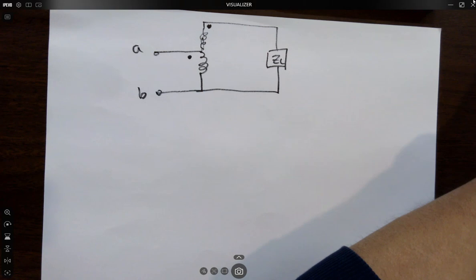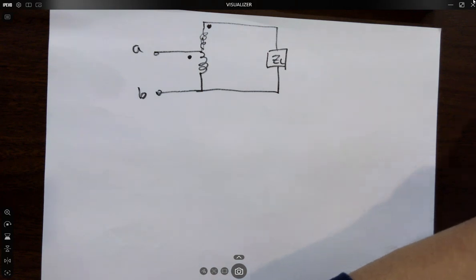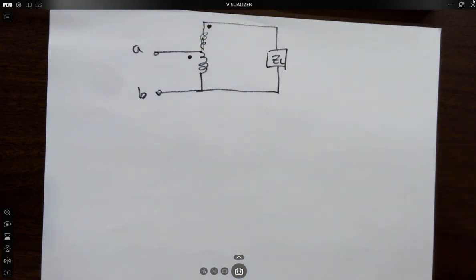Just a blinking LED of the audio signal of the song, received by the little solar panel. And the solar panel converts that blinking light signal into an analog voltage, and I use an audio amplifier to amplify it, and I can play the music using the solar panel that receives a blinking LED. It's a really interesting experiment to play with. So there's no connection, it's just a solar panel and a blinking LED, and it plays the music from here to here.